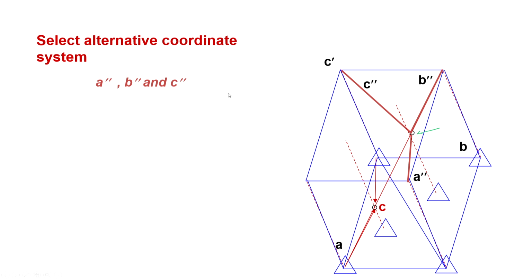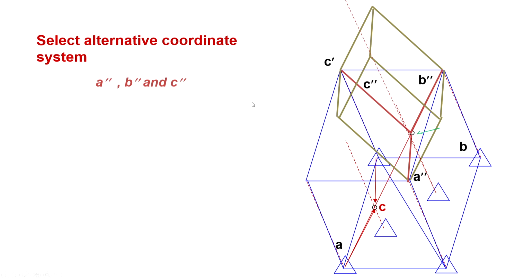So, they are constrained in that way that all the 3 are equal, and the angles between them will also be the same. And the unit cell that you get is looking something like this. If I extend this threefold rotation axis, it goes from this vertex to the opposite vertex out here. So, it is basically a body diagonal inside this cell.